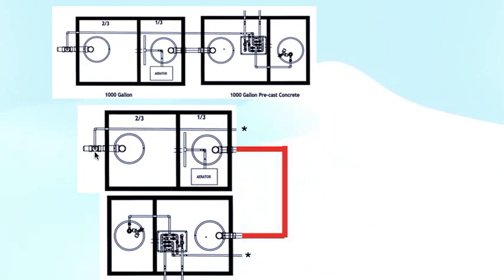It's always going to be pressurized, so no need to use 45s and worry about friction loss. Just use elbows, keep it straight, keep it clean, but that's where that will be going. But either of these tank arrangements are perfectly fine. That's what we're looking at there.